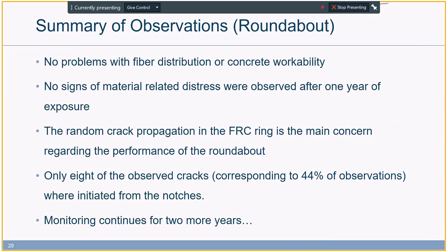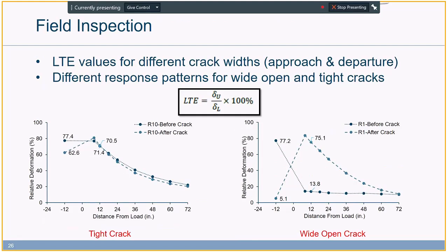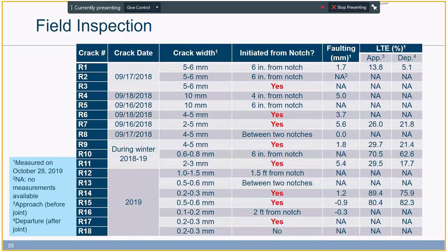All right, thank you. I'm just curious, some of the cracks are like 6 millimeters, right? Yes. So if concretes are pulled apart by 6 millimeters, the fibers either pull out of the concrete or they're just really plastically elongated.